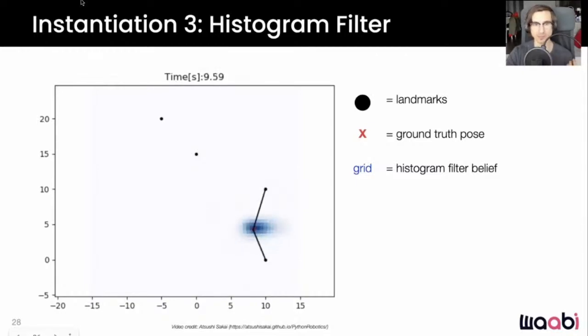And note how the shape of the probability distribution starts off with that ring-like pattern, where the robot only senses a single beacon, so its location around the beacon is very ambiguous. It then converges to this unimodal estimate as soon as the robot sees another beacon, which reduces its ambiguity. Note that as the robot moves around, the shape of this distribution is very non-Gaussian, so a Kalman filter would struggle to model this example.